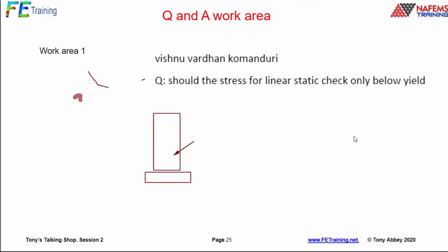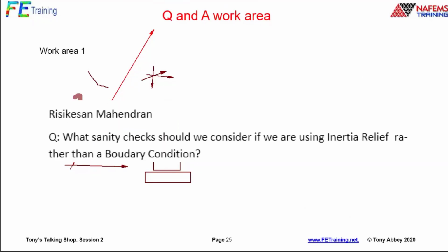It doesn't mean anything. If you remember, for the stress strain curve, we've got a linear analysis stress strain curve, and I went through all of the annotations for the diagram, but we're saying we go up there. If we do bilinear, we go up here. That's a non-linear analysis. And what a linear analysis does is to say I'm going to completely ignore that, and then it just basically says, here's my solution. My solution just goes up here and just goes onwards and upwards. So it becomes physically meaningless. So that's really the point in there.